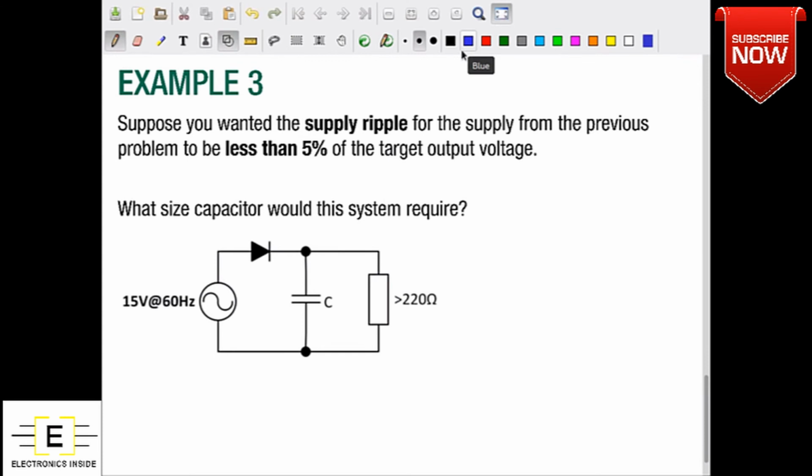Alright, so finally let's tie up that last little hanging thread from that first problem. Now we're going to sweep back around and pick up that thread we mentioned in that first problem. Remember, we looked at this particular circuit with an output filter capacitor that was 470 microfarads, and we found a rather ghastly figure of approximately 2.31 volts of ripple on that supply output.